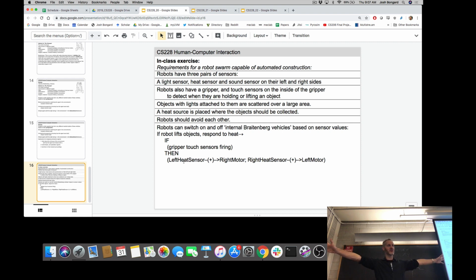At the beginning, maybe we assume the light sources are distributed more or less uniformly across a very big surface area. But as the task progresses, there's going to be a greater and greater concentration of one of the stimuli to which the robots are responsive. So we may propose to the engineers a change that the lights are turned off at some point. Or alternatively, we add some complexity to our robot controller, which is if there's a lot of light but also a lot of heat, then ignore the light. There's different options here, but again, that's a good observation about context, which matters.